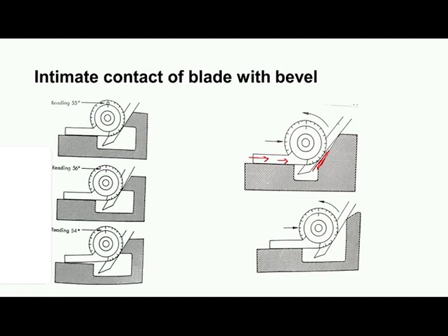We should clamp the blades, and then we should take out, and then we can read the instrument. If we further push the instrument, you can see here when we push, there will be a proper contact like this, and if we try to push further, again the sliding blade further rotates, and then there will be error in the reading. Such things should not be there.